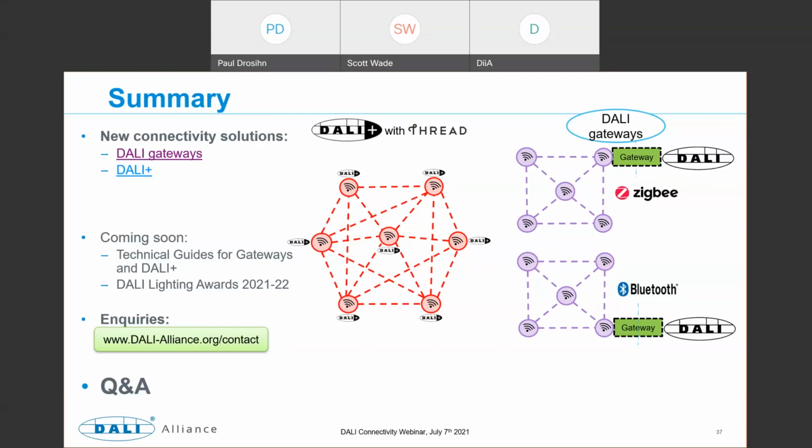Of course, you can also make a DALI Plus sensor, so it's directly in the system. So a DALI Plus input device, its event messages are all used by any of the products in the DALI Plus system that want to use those event messages, or they can use polling if they want to. So yes, assuming it's wired, you would use a bridge, and that allows the sensor to be part of the DALI Plus system effectively.